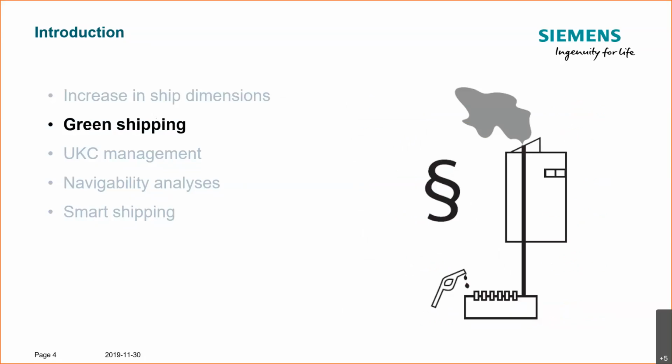So decreasing power on a ship brings to the attention in the context of maneuvering if the vessel will still be able to meet the maneuverability criteria in adverse conditions like a storm, waves, wind, or in shallow water. Because apparently with less power, that is a direct concern to the ability to change or keep a course or make a turning or stopping maneuver or attain a certain speed.